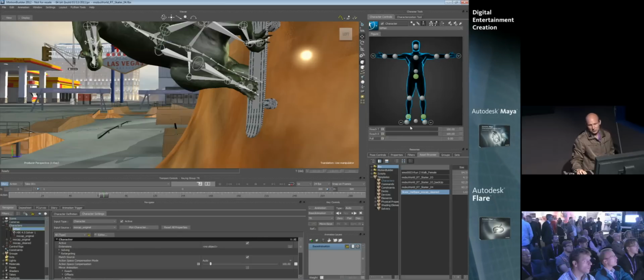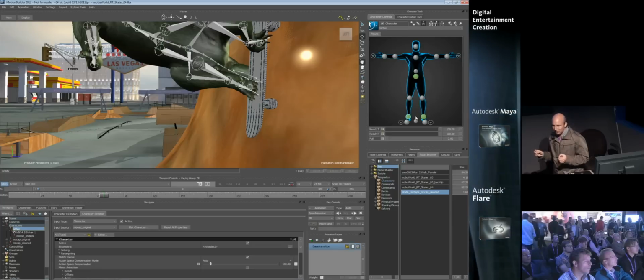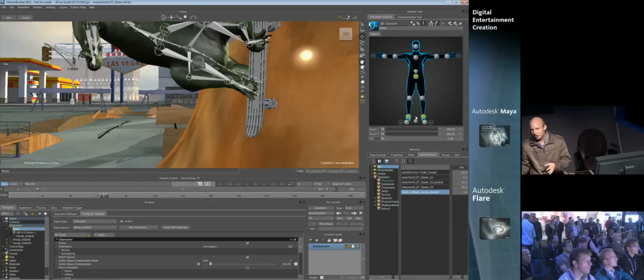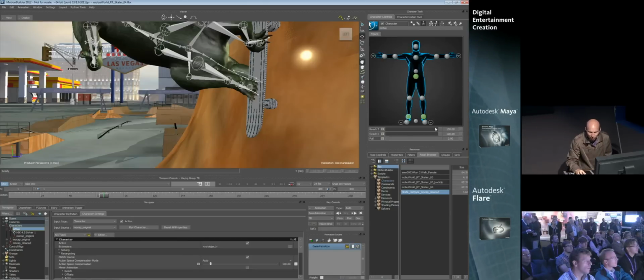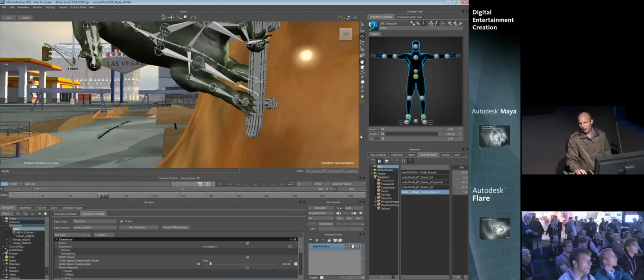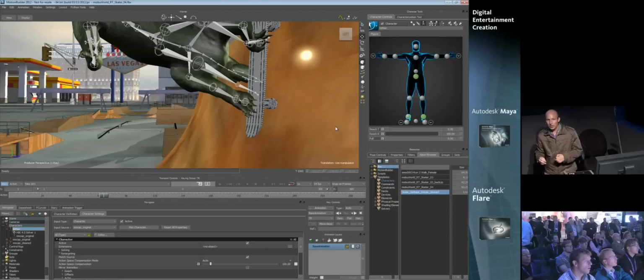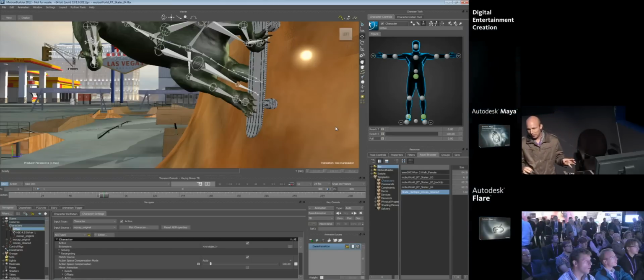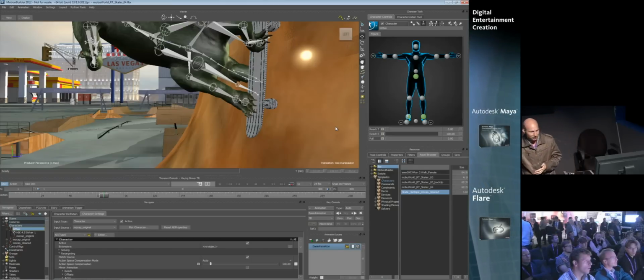That's because when I turn match position on, the character's feet have the little green circles. The little green circles mean that I'm no longer concerned about matching joint angle. I'm more concerned about matching in position, or the IK handle if you would. So obviously if I drop that value down, I'm now matching joint angle. At any given time, while we're doing this retargeting, we can tell Motion Builder what we're more concerned about, joint angle or world position? And obviously his feet need to hit the skateboard, so world position is very important.